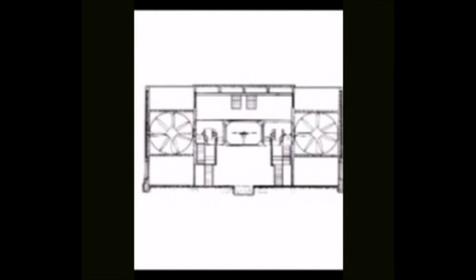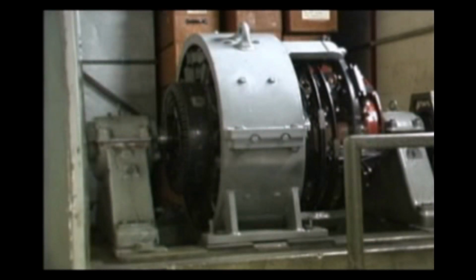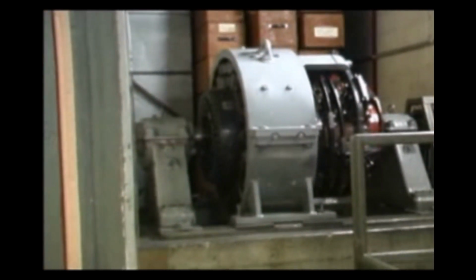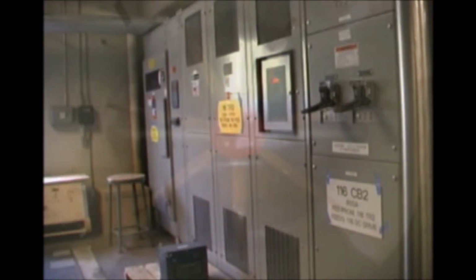The tunnel is powered by 2 variable speed 500 horsepower direct current electric motors located on the fan decks. The wind speed is controlled by varying the electric current to the motors, thus adjusting the motor RPM. The electricity is supplied by a solid-state 12-pulse DC drive capable of outputting up to 600 volts with less than a tenth of a volt resolution.